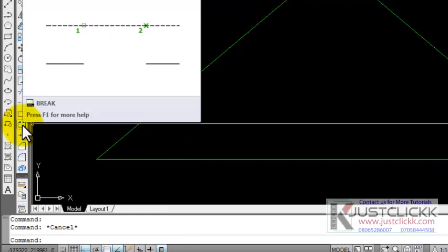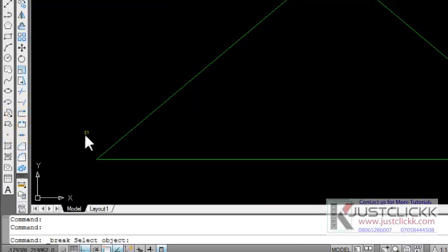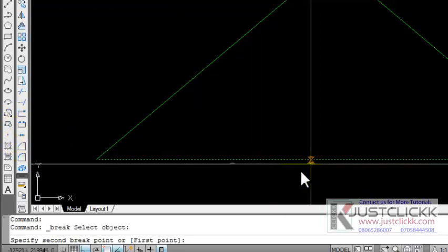As the pictorial view you see here, it breaks with an opening. So it is very useful during wall creation, during walling your design. You can use it. So let's use an example here of how it works. You select the tool, and select the target object. Mind you, we're selecting this one. So I want a break